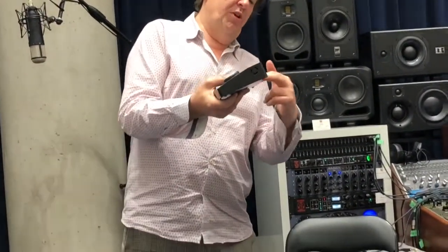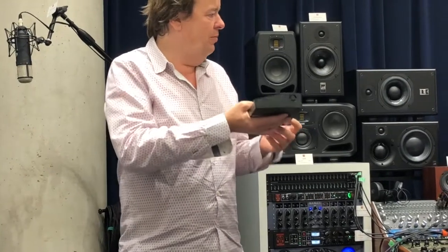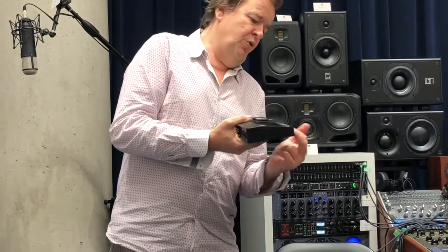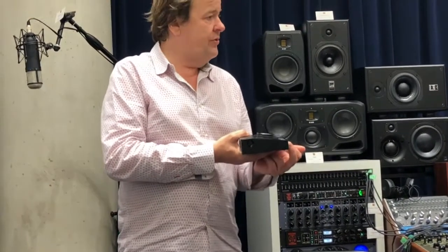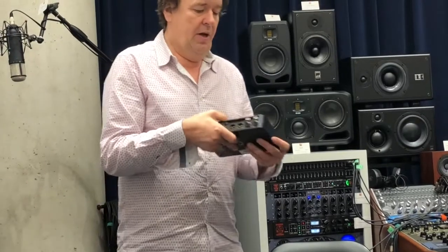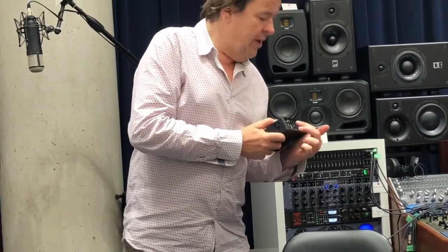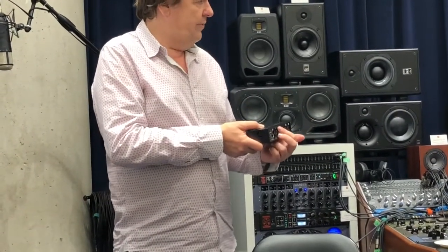You have 2 mic pre's per input together in a line, so that means you can go up to 137 dB dynamic range. So it's very comfortable on that aspect. You don't need to wiggle much about the gain. These are the inputs. You have 2 inputs here, 3 and 4, which are line inputs or high impedance instrument inputs. Then you have 2 outputs here, XLR symmetrical, and you have 2 jack, but also symmetrical outputs, 3 and 4 there.